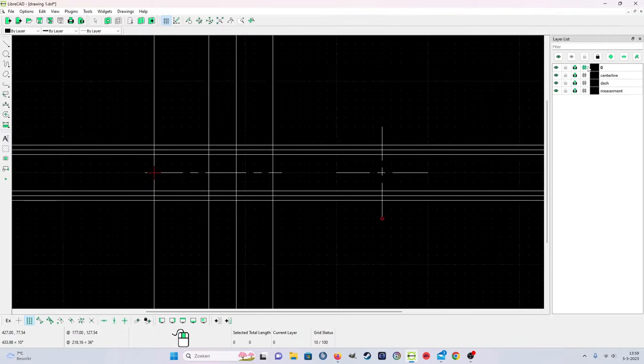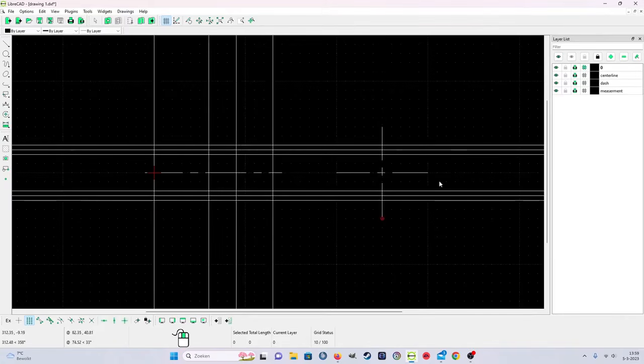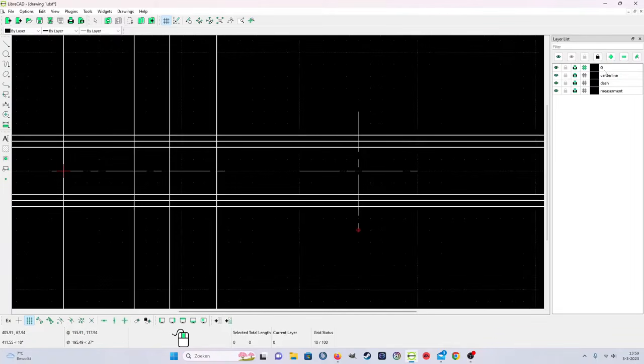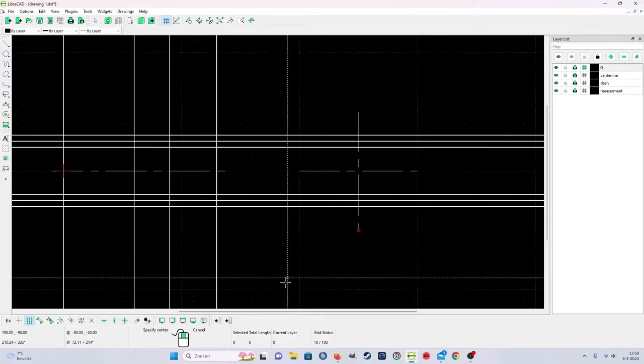You see? Just on the small square of the lines you want to... Okay, if you use the center lines, then it always does the center lines. But the drawing lines, because I want to copy the drawing lines. So I select the 0, my drawing line. Then I'm going to put the center to point. That means from the middle to the first line, I want to copy the circle from center point.